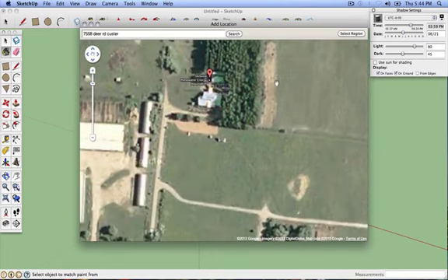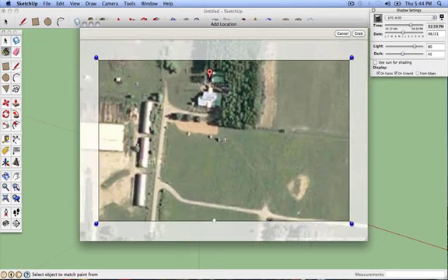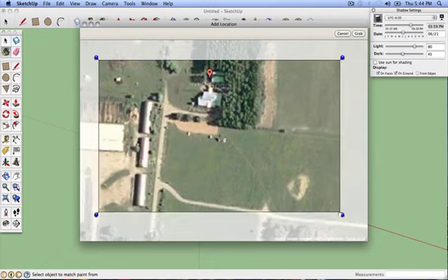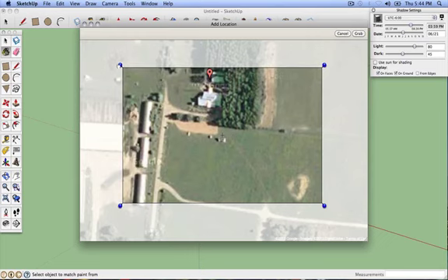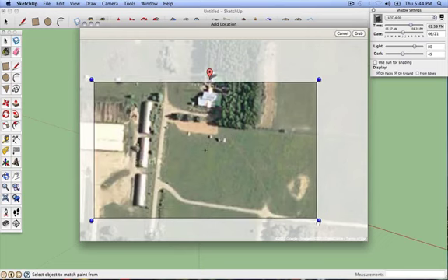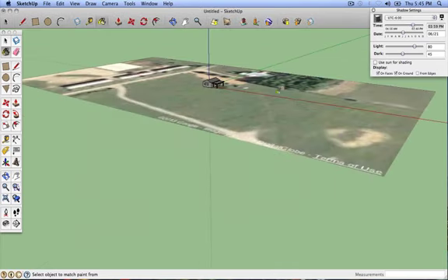To select the area you want to put in, select region, which gives you the ability to zoom in of the area you want to put into your drawing. The crosshairs will be where the red and blue and green line is. When you have it all set, just hit the grab and it will drop the location into SketchUp.